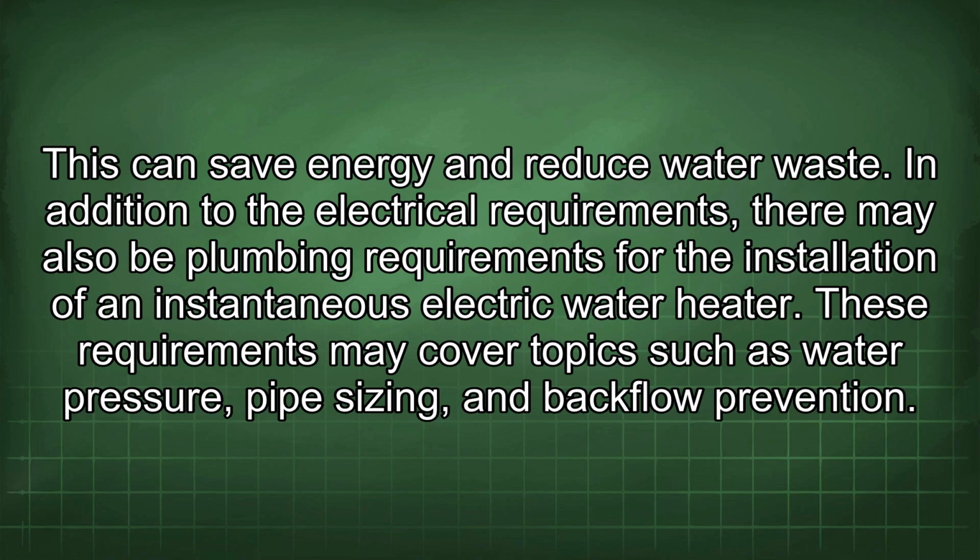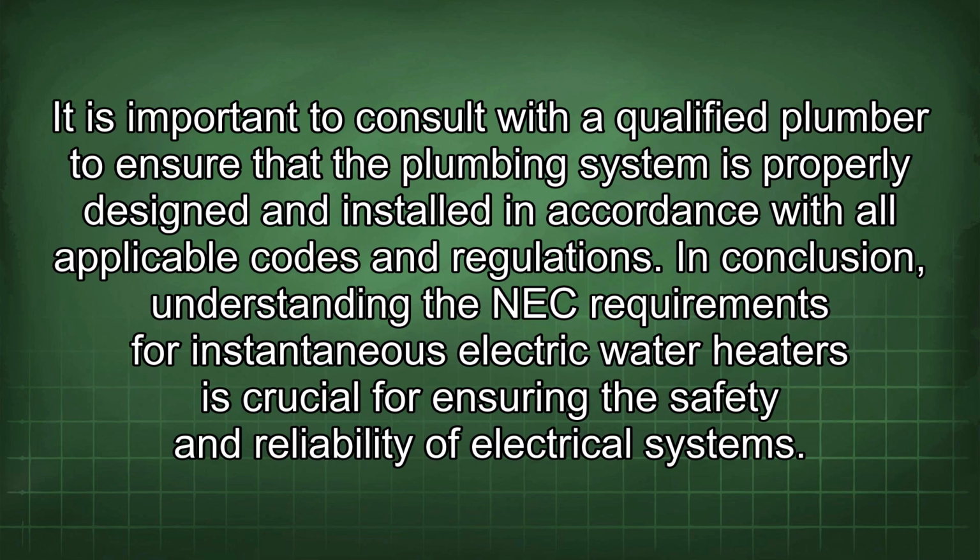In addition to the electrical requirements, there may also be plumbing requirements for the installation of an instantaneous electric water heater. These requirements may cover topics such as water pressure, pipe sizing, and backflow prevention. It is important to consult with a qualified plumber to ensure that the plumbing system is properly designed and installed in accordance with all applicable codes and regulations.